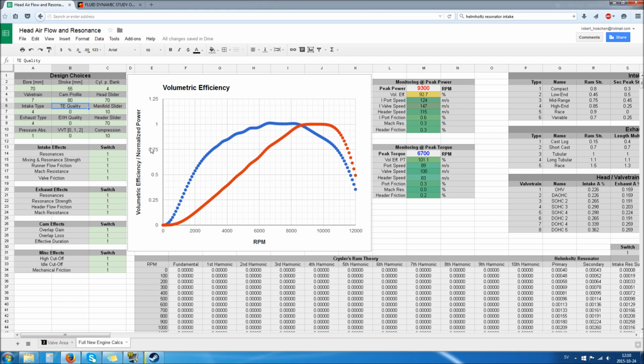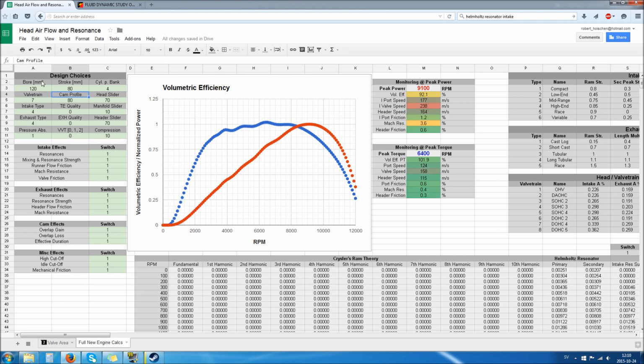So, I would say we've achieved our goal, and now we just make a big one out of this and see what changes. So if you could rev this one that high, go for 80 here. You would in general just shift down the torque curve overall for a larger engine, because it quicker goes into flow limitations and in general is not so happy about supersonic flows. So yeah, that's that. And of course if it got a 120 bore, it would probably valve float before then. Alright, so that was the 3 engine types, just for showing that off, and now we are going to take a bit of a look at various individual effects and how you can steer them to benefit your engine and not limit it.